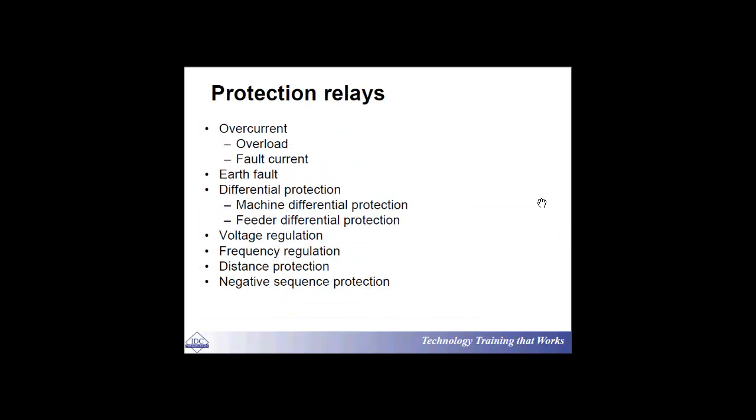So the first thing is that you need to understand those IEDs. I've already talked about PLC. I've already talked about RTU. What about relays? Well, modern relays we are talking about, right? Obviously, I'm not talking about those very old induction type, disk type, electromechanical relays. No, I'm not talking about that. I'm talking about modern numerical digital relays. They are IEDs. They are the ones that can be connected to SCADA, RTUs, PLC, comms, smart meters. This is the thing I'm talking about.